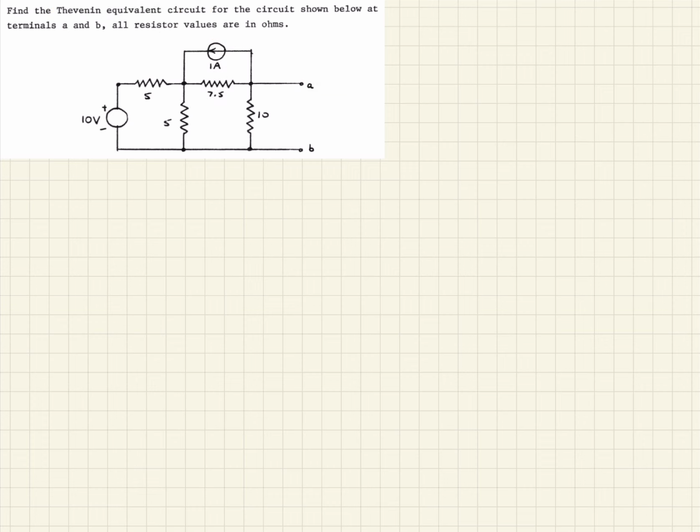So the first thing we want to do is to calculate the Thevenin resistance, and so that'll be RTH, and that'll be looking back into our circuit here. So we recall when we do that, we open circuit all current sources. So this current source here would be as if it's not even there, so we'll open circuit that. So that's gone. And then voltage sources we short circuit when we're calculating the resistance. So in this case, we will short circuit this.